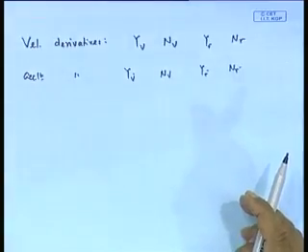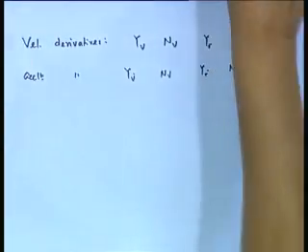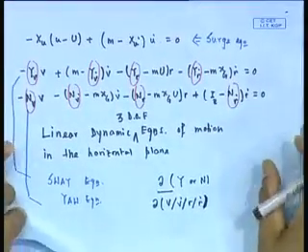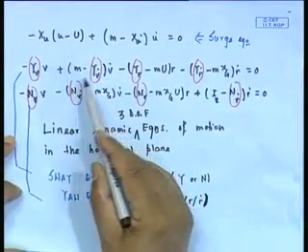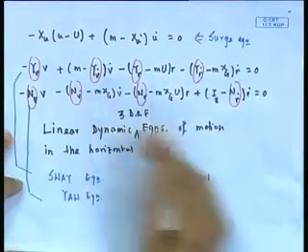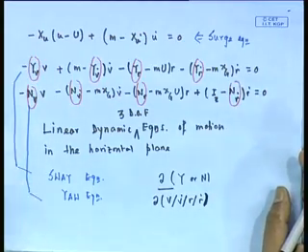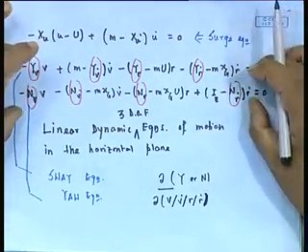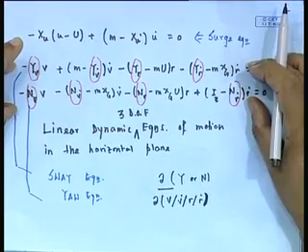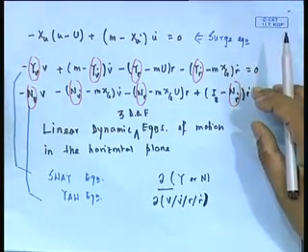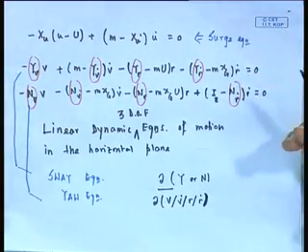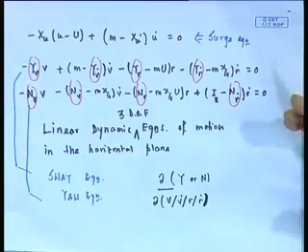But remember why it is important: if we go back to the equation of motion, we need to know whether they are positive or negative, because this has a bearing on how the equation of motion will have a solution, just like your metacentric height should be positive. There is a condition that comes out for stability purpose.